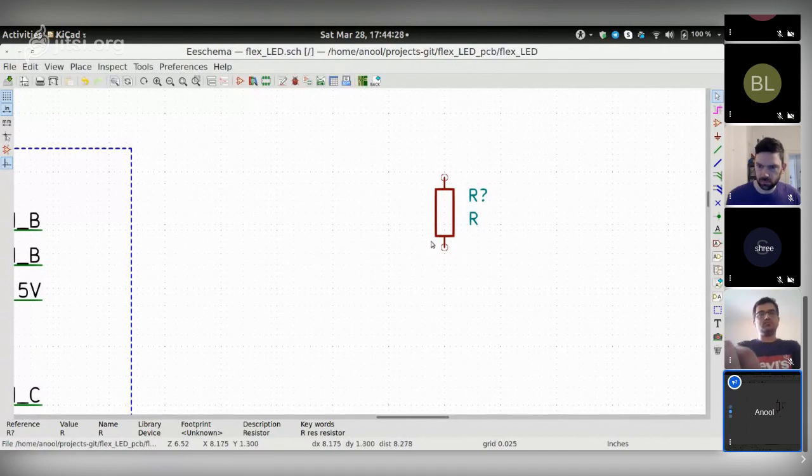And if the global symbol now changes, let's say for some reason they decide to increase the length of the pins, that's going to break your project if you were to use that. But using this method, no matter what happens to the global libraries, you don't care. Your project is embedded with a local library and always works no matter who opens it, or even if you open it up 10 years later or something like that. So that's a great way of making sure your project works.